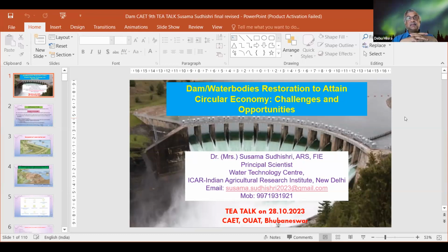Susama, I see a problem with your approach, and the problem is this: first of all, drying the reservoir is not an easy job for a large reservoir. Yes, you are talking about smaller structures like a pond or soil conservation structures where we can dry it successfully. But Hirakud Dam, drying the Hirakud Dam, where are you going to place the water? Downstream? That will cause flooding, right? Yes. So that is number one problem.